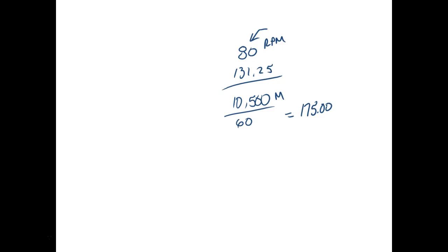So a software counter is implemented with programs, right? You understand? You can imagine the amount of code it would take to do counting. So the big advantage of hardware over software is hardware is a lot faster, but you're stuck with what you got, right? So what they've done on these PLCs is they put what we call high-speed counters. These are hardware counters. So now our PLCs have these extremely high-speed counters in there, and they're implemented with hardware, which means they can go at an extremely high speed, right?